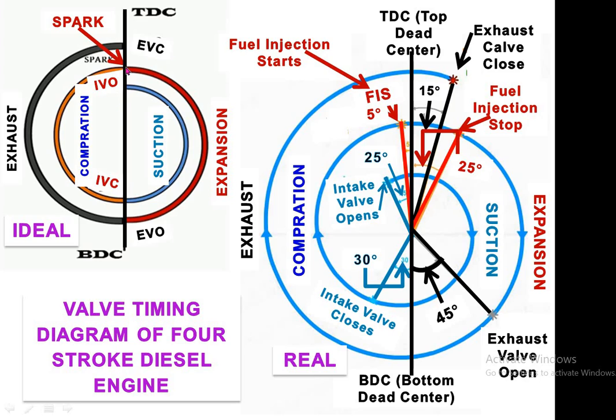So at that time, there is a high temperature as well as very high pressure, and at the same time, through the fuel injector, we are injecting fuel inside the clearance volume of the cylinder. As the fuel is injected, due to the high pressure and high temperature inside the cylinder, or we can say inside the combustion chamber, the air-fuel mixture automatically ignites. There is no need for a spark plug, because the temperature of the compressed air is high enough to ignite the air-fuel mixture. Due to this the air-fuel mixture ignites, and the expanding gases push the piston to the downside.